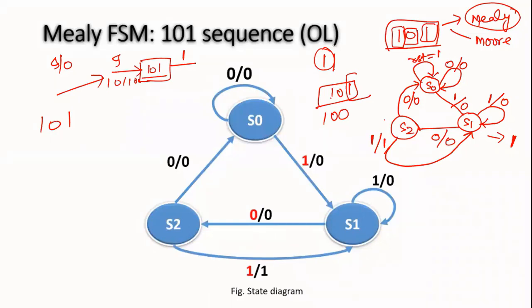The first job is to make an FSM. It is going to go through different states. Why different states? The reason is I am getting one bit at a time. It is something like buying a 10 rupee railway ticket with coins: I am supposed to get 1 rupee, 2 rupee, 5 rupee, like this. I keep on getting them one by one, and I reach that 10 rupee. The same scenario here, 101. So the first state is the initial state. Whenever people give reset, it is expected to be here.